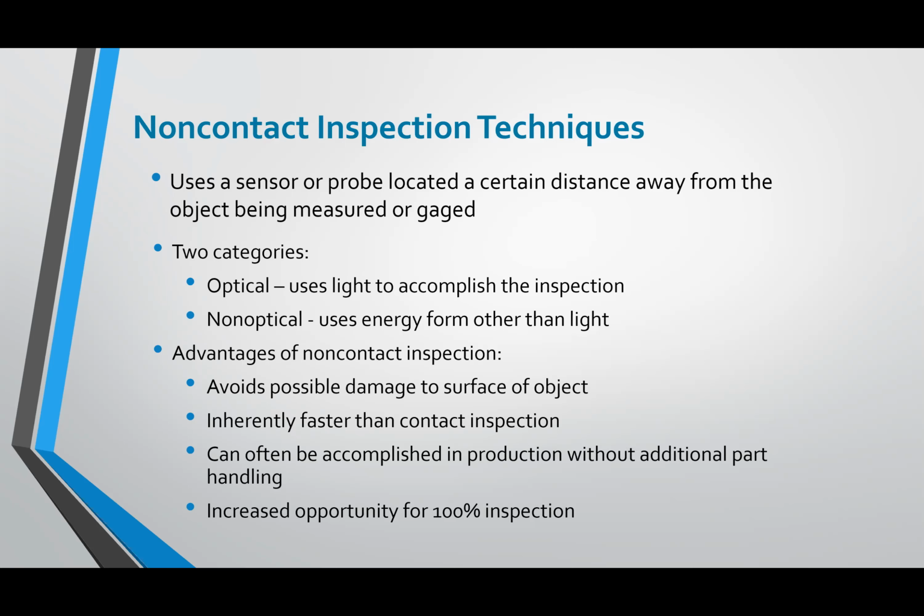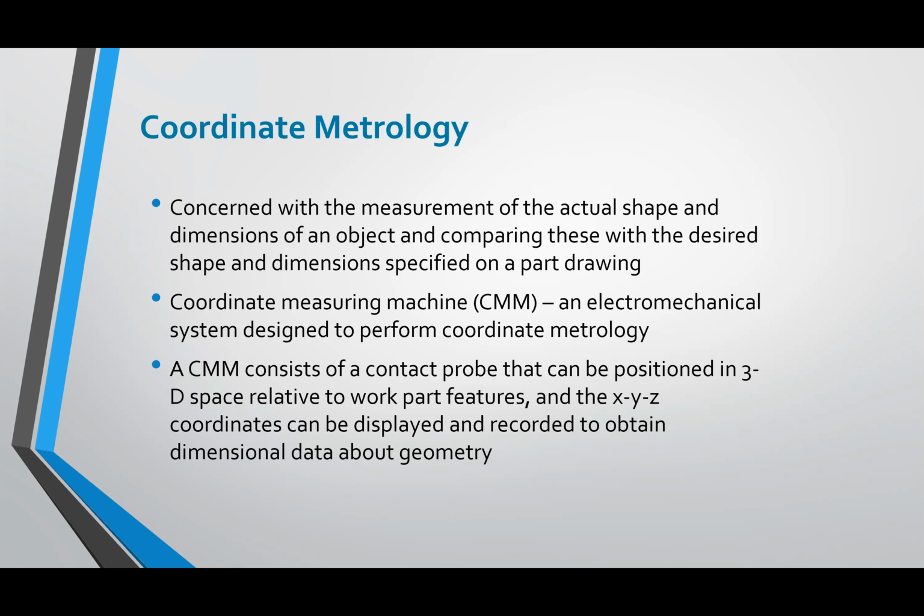Non-optical is a device that is a non-contact device, but that is not using light. And so when we look at the CMM machine, the coordinate measuring machine, that's an actual probe that will be able to measure all of the dimensions of an object and compare them with a part drawing. So instead of having an individual measure the part for each of those dimensions and compare them to a drawing, you can upload a CAD drawing into the computer, and then the coordinate measuring machine will compare the physical part